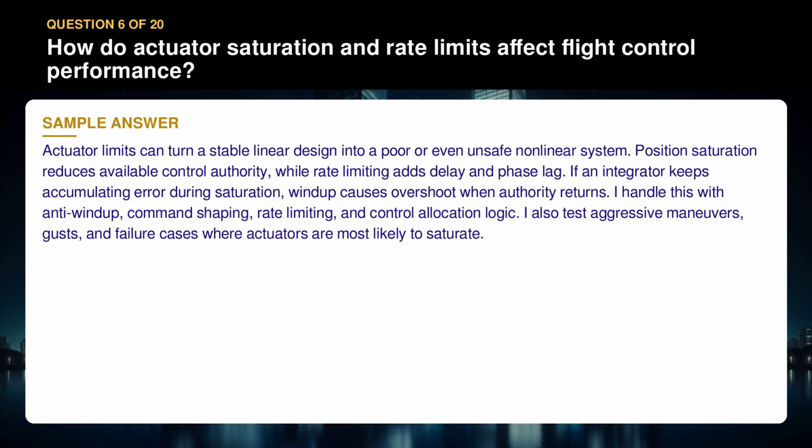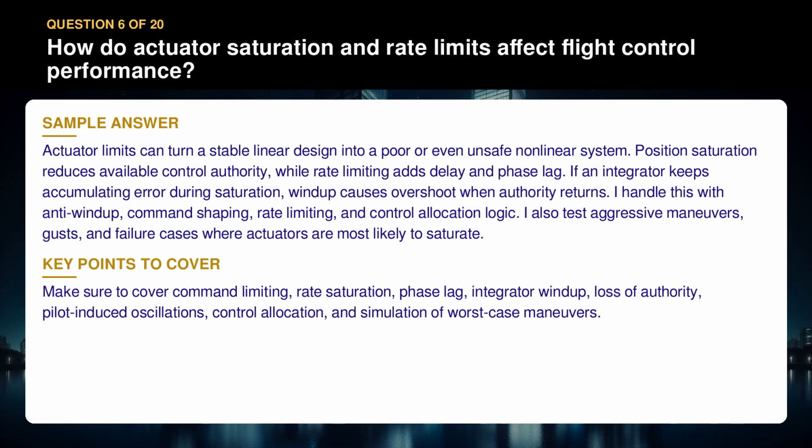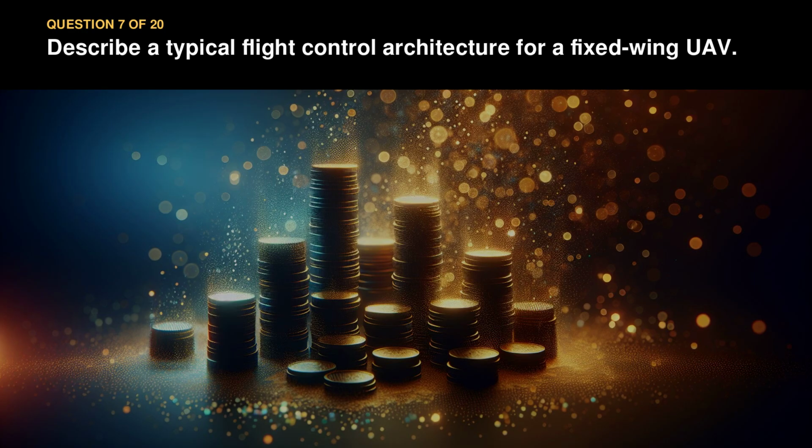I handle this with anti-windup, command shaping, rate limiting, and control allocation logic. I also test aggressive maneuvers, gusts, and failure cases where actuators are most likely to saturate. Make sure to cover command limiting, rate saturation, phase lag, integrator windup, loss of authority, pilot-induced oscillations, control allocation, and simulation of worst-case maneuvers.